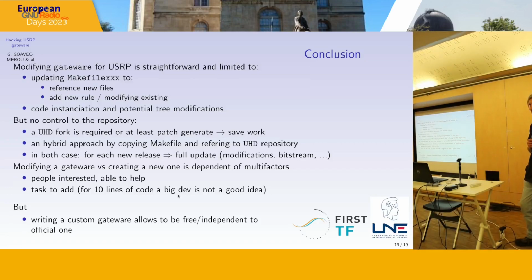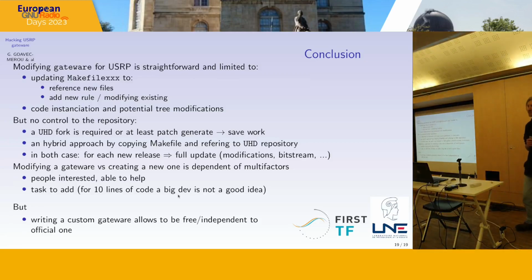But actually, a question about this setup. So you're injecting the PPS into an RFNoC block. I guess a question and comment, something to be aware of is there's going to be non-deterministic latency between the ADC capturing and your RFNoC block, because there's actually a switched bus in there, so you'll get variation there. The other thing that you have available within an RFNoC block is the timestamps of the individual samples. So you can actually read what the timestamp of the first sample in the buffer that you're processing is.